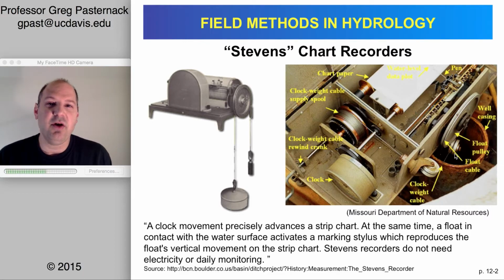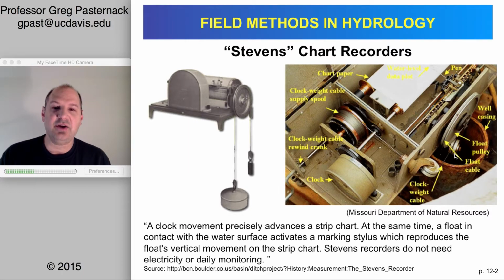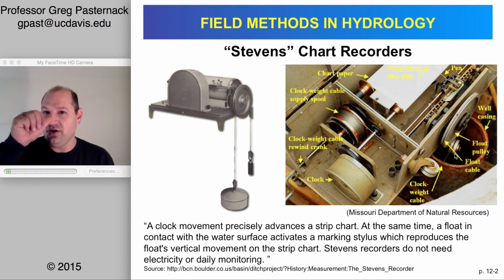So through really interesting mechanical means, there was the ability to transfer a natural signal to mechanical work to something that's documented on paper. Usually the clock could run for a week, so once a week someone would have to come out, usually recover that piece of paper, put in the next piece of paper, and wind the clock, just close it up, keep everything oiled and in good working condition. And that was the primary job of a hydrologist in the field after installation, was to basically just get out there regularly to keep the thing going.